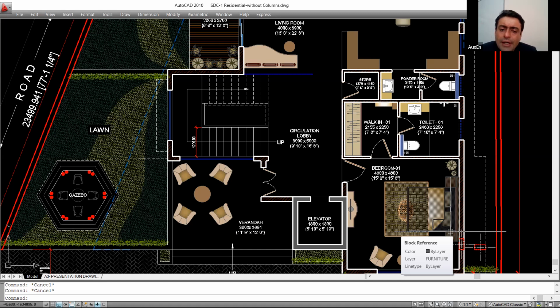So an 8-inch thick brick wall offers you more serviceability with respect to the weather, rainfall, seepage, etc. Therefore you would like to have your external walls 8 inches thick.